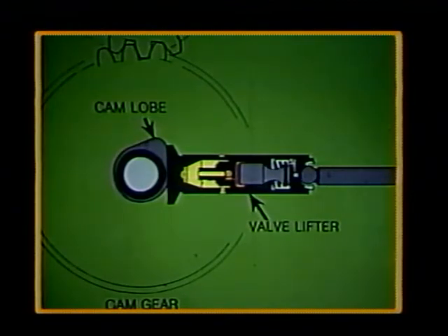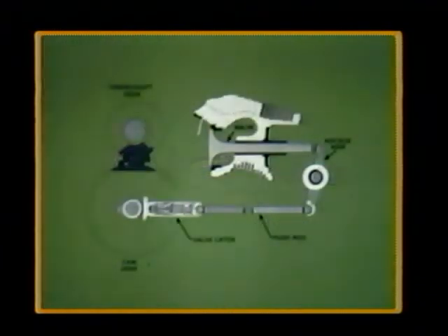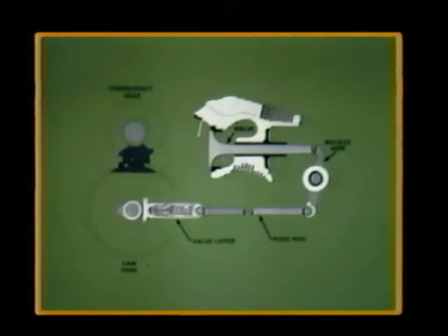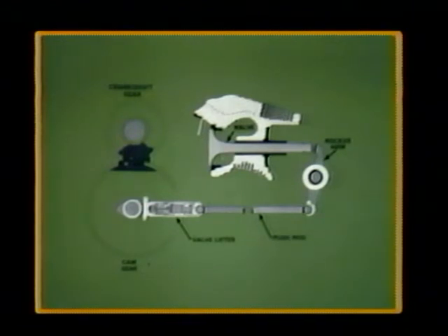Now, as the cam pushes up on the cam follower, the check valve seats, trapping the oil in the body and forcing it to serve as a link in the valve operating mechanism. By using hydraulic valve lifters, we are able to maintain zero clearance in the valve train. This improves volumetric efficiency when the engine is cold, and since there is no lash or space between the moving parts, there is very little noise or wear in the valve train.